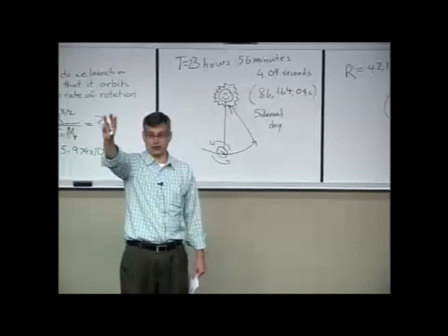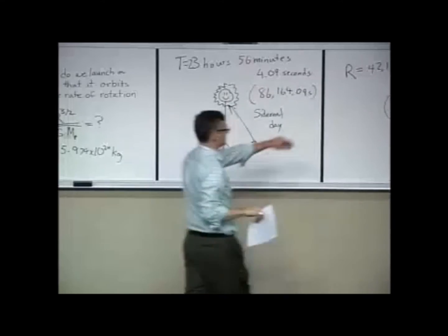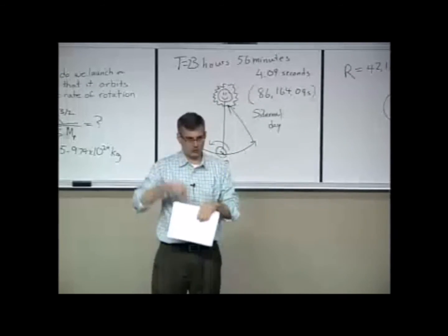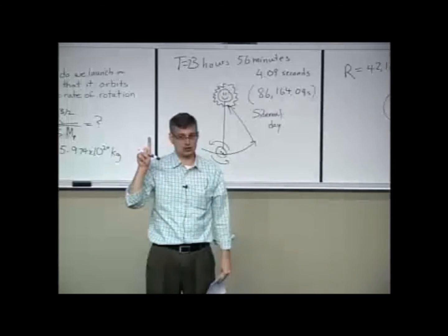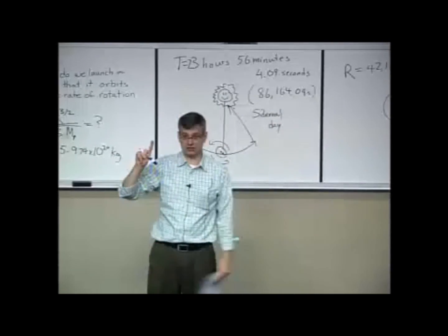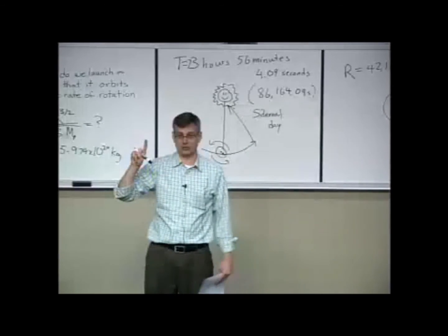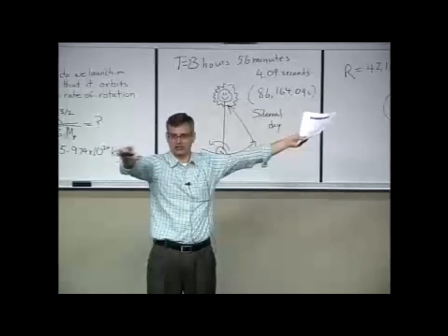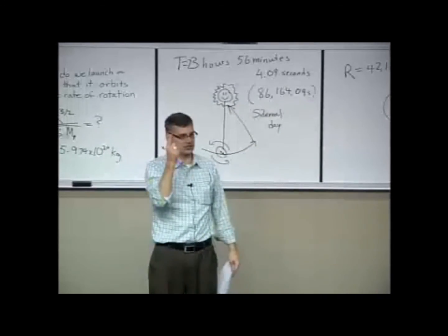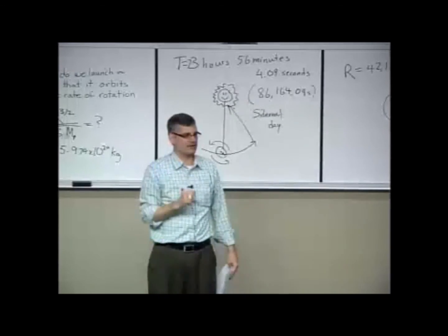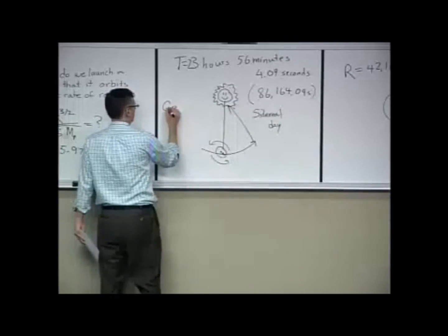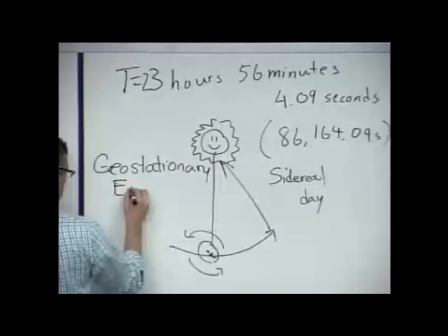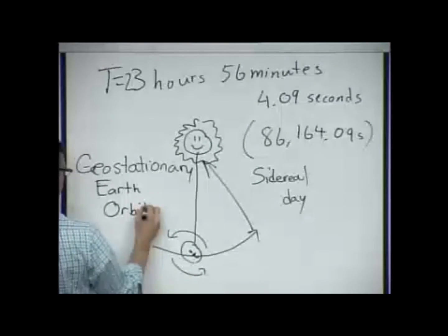Well, okay, there are 3 conditions, actually. If you make the orbital period a sidereal day, you have a geosynchronous orbit. Means the orbit will repeat itself every day, but unless it's a circular orbit, which is the condition that we just found, we derived that equation using circular orbit, so we got a circular orbit answer for the radius. And it has to be equatorial, aligned with the equator so that it tracks around. If you do those three things, geosynchronous, equatorial, circular orbit, then you have a geostationary Earth orbit.